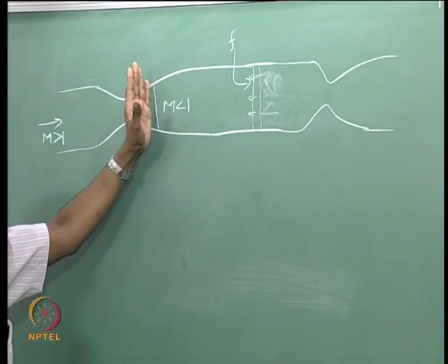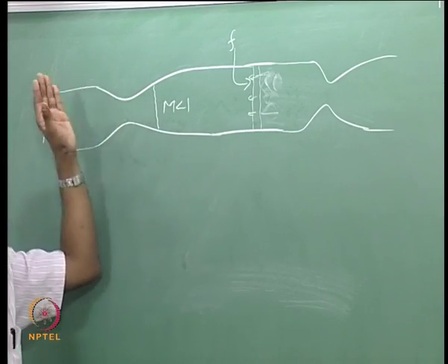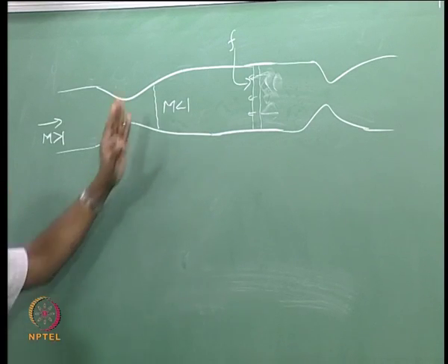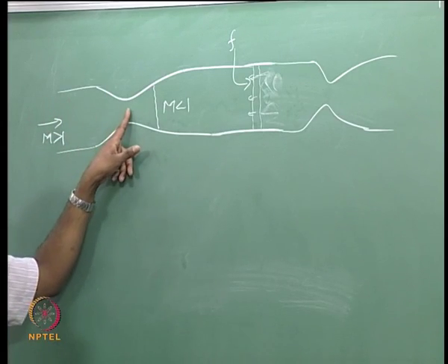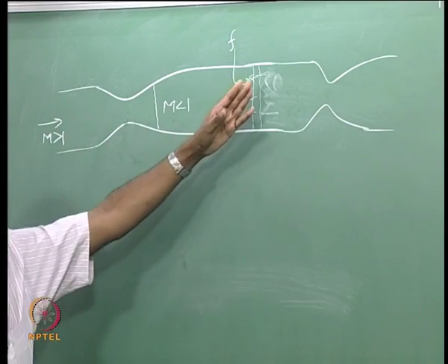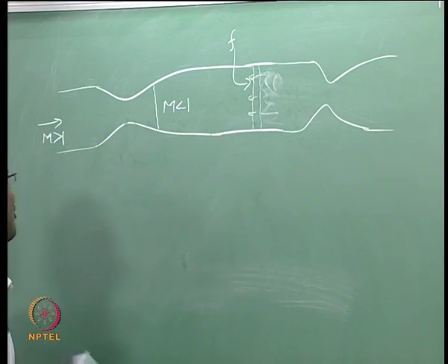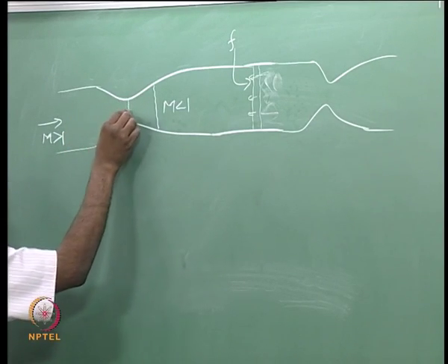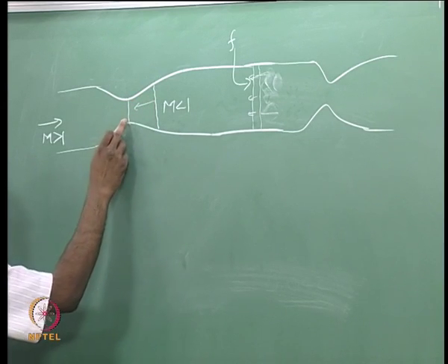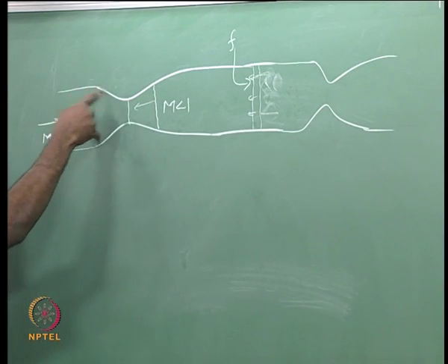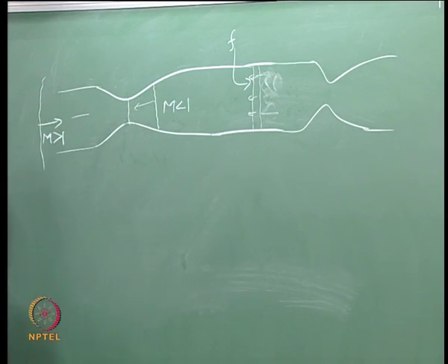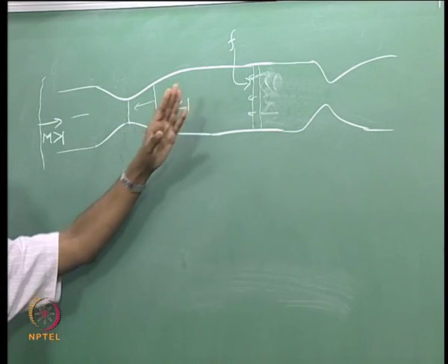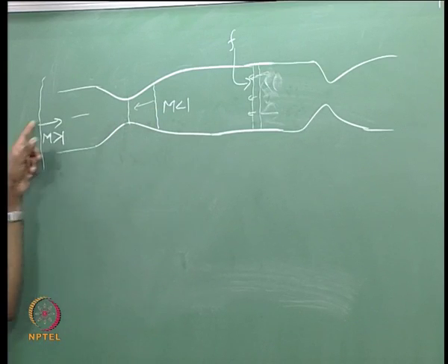Now the shock goes and sits more and more upstream. There will be a point where the shock reaches this thinnest point, that is a critical condition. If I go anywhere more upstream, when I send more compression wave, then this shock keeps moving like this. After this point, you know that it is unstable in this converging duct. So what happens is suddenly it jumps out of this whole thing and sits here. Basically I introduced too much fuel, that compression waves came and pushed this shock ahead of this whole thing.